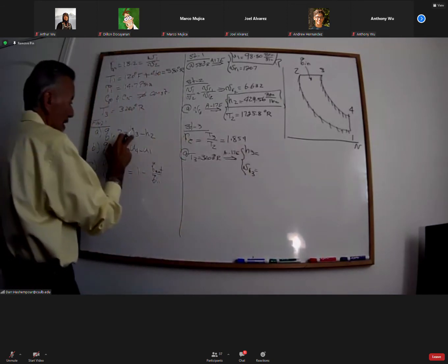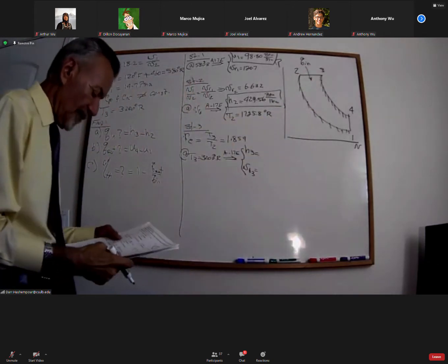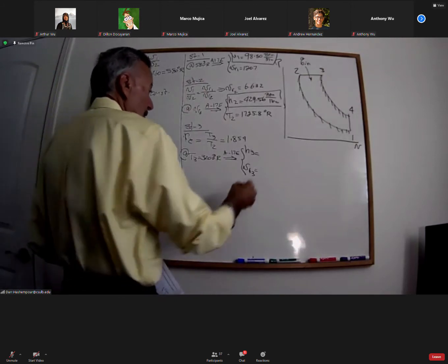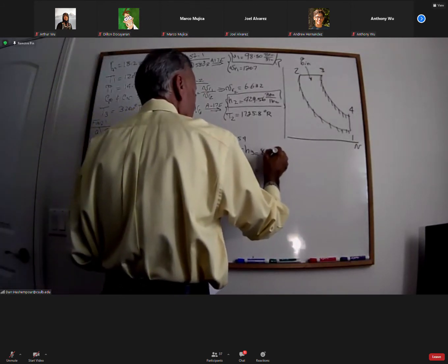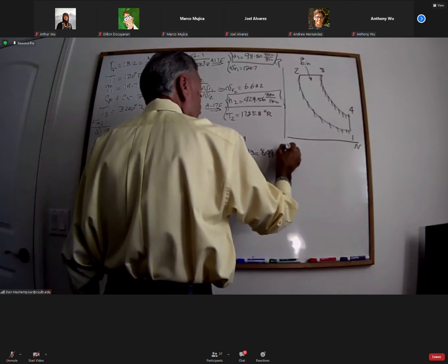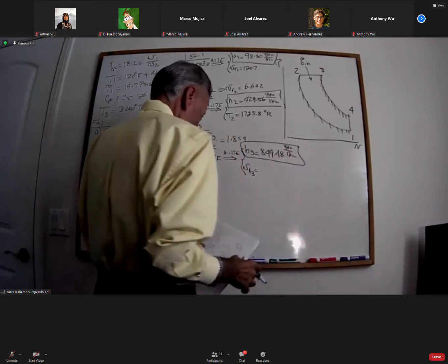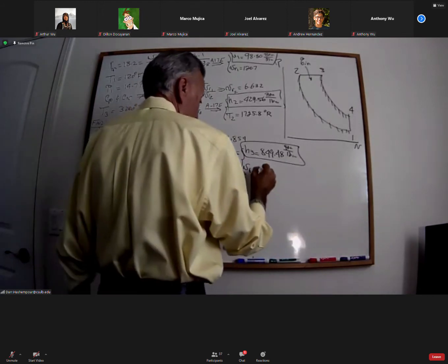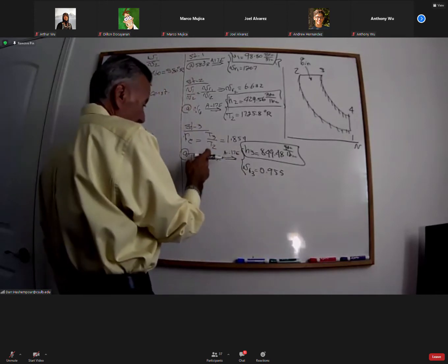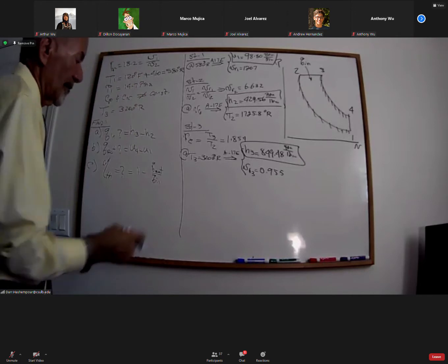This time I find H3 and VR3. Why H3? Because I need H, and this is at a constant pressure. I don't want to find a U value. If I do that, the H3 would be 849.48 BTU per pound mass. That's my third parameter. And the VR3 is 0.955. Check these values on your table, and see if those are correct.